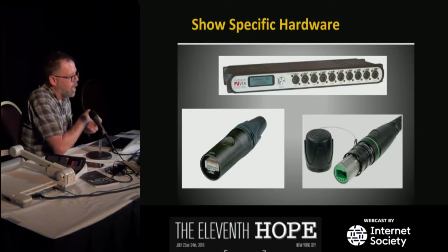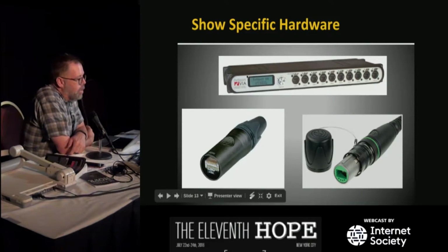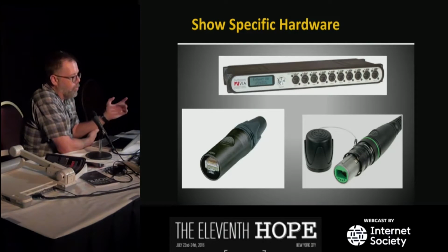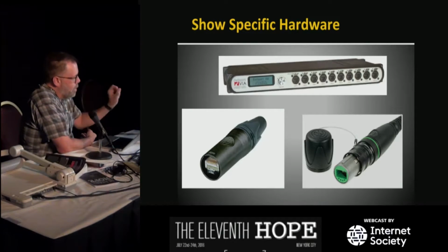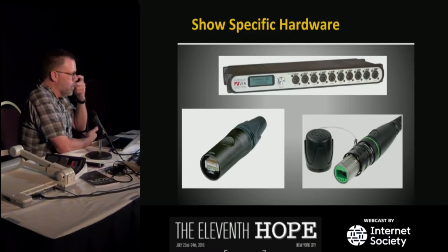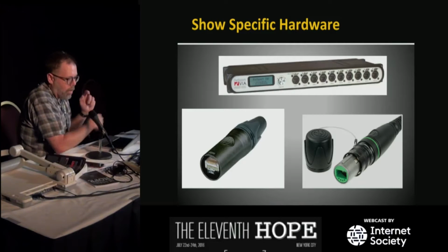All those things. And then it just has a knob so you can set some VLANs in there without having to go to Cisco school or anything like that. You can also set it up to just be aware of the protocols we use, so some lighting control protocols, some sound ones. You just say, hey, I'm running Dante on this thing, or I'm running streaming ACN, which I'll talk a little bit about. Boom, you're done. You don't have to go figure out how to do it and accommodate it. So again, we mostly do systems integration and try to put all these things together.